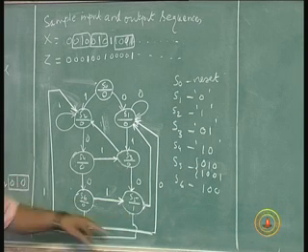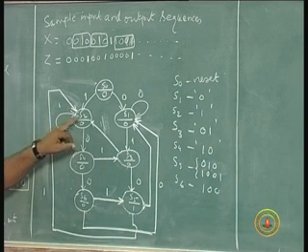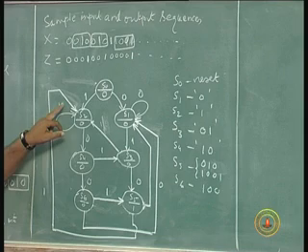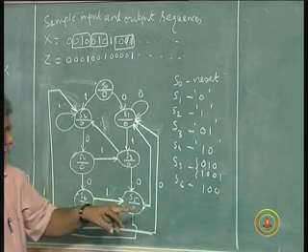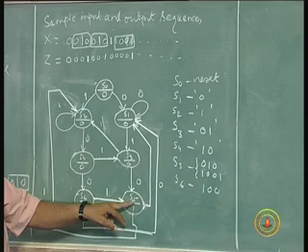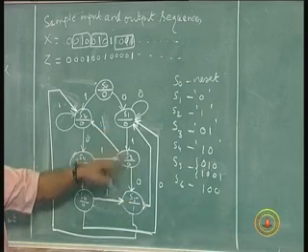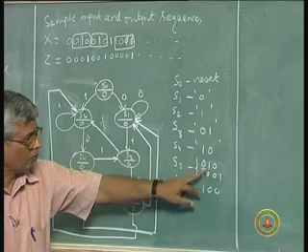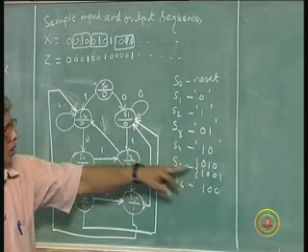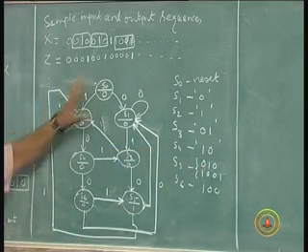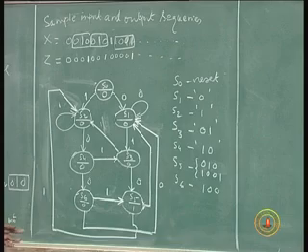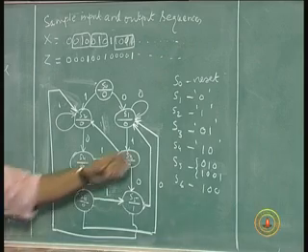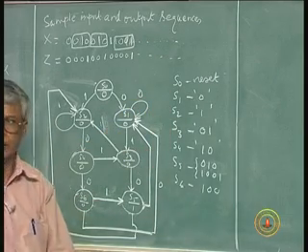So, 1 will take it to this new state S2, which starts a new pattern with a 1 for 1 0 0 1. If 0 occurs, it takes us to state S1, which is the start of a new sequence 0 1 0 here. Now, the diagram is completed, it is 6 states plus 1, 7 states totally.